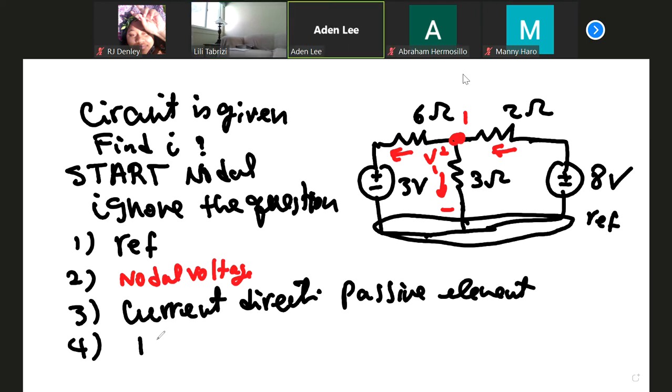Here, you have to write the KCL equation for all essential nodes. In this case, we only have one equation. When you write this KCL equation, have a quick assessment. When you look at the circuit, the essential node, we only have node 1. How many currents are entering and how many leaving node 1? There's 1 entering and 2 leaving. Entering equals the summation of leaving. That's KCL, right? Let's start with the entering one.